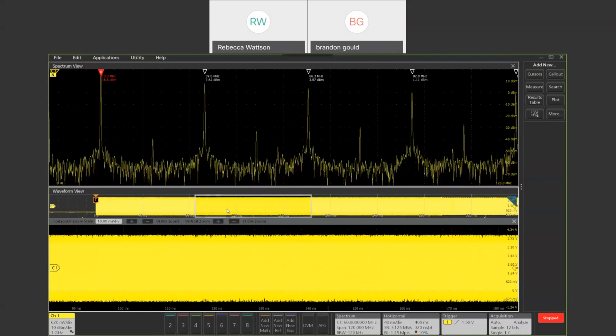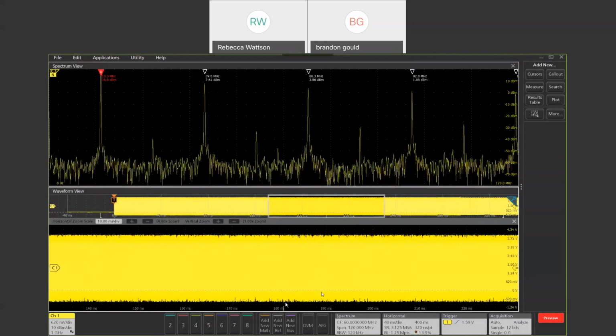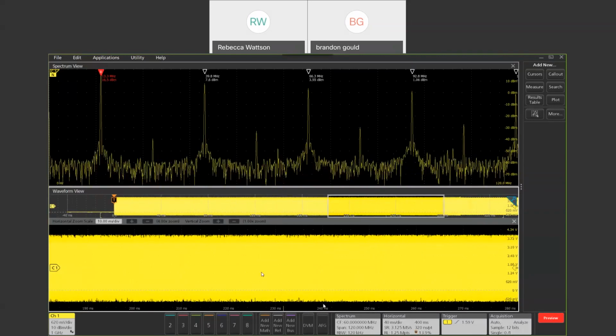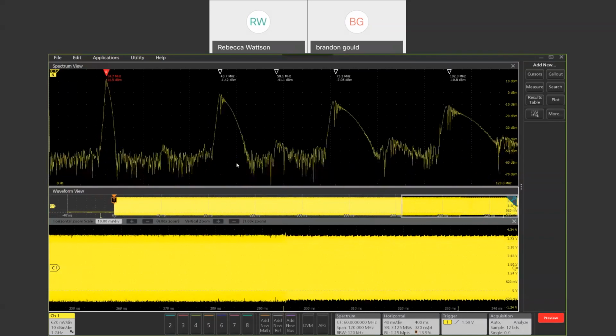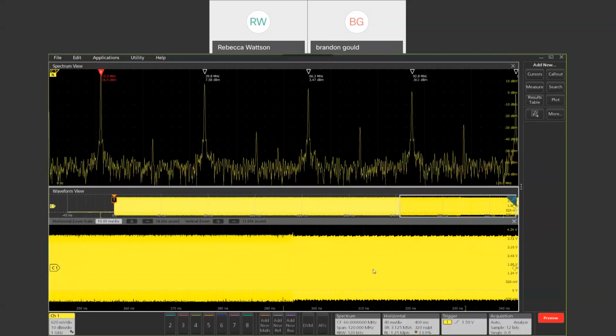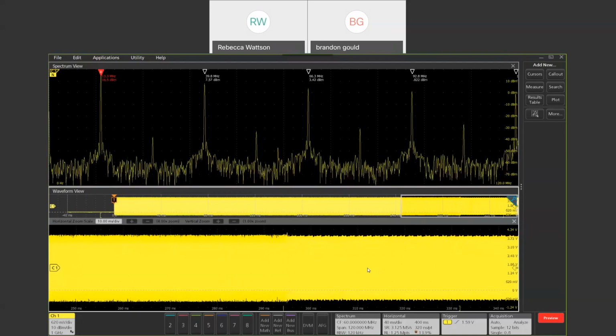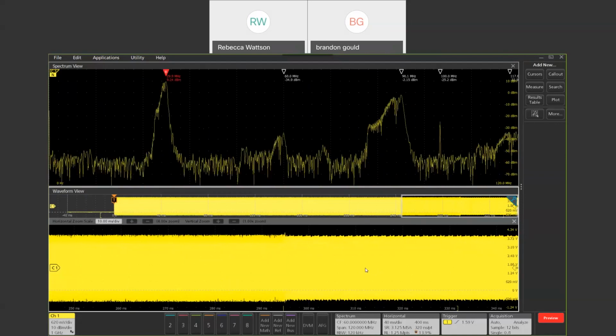We're at 100 milliseconds after the board was plugged in. About 200 milliseconds down here now. 230, and I'm not really seeing any change in my spectrum up until maybe 290, 295 milliseconds. So it's quite a long time for the spread spectrum clock to start to come up, but let's look and see exactly how quickly and what the interaction is for when it isn't on until it's in its steady state behavior.